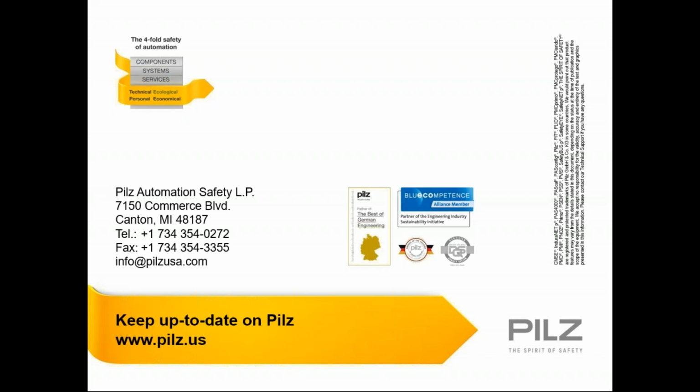Randy, this is Ben. The only thing I would mention very quickly is that in your pictures where you were demonstrating the circuitry for different category levels, the illustration shows 2 mechanical gate switches in order to meet the redundancy requirements for those safety categories. I would mention that if you use a higher safety rated, a category 4 safety rated switch, then you don't need to have 2 switches there. I just wanted to make sure that that was clear and no one was misled by the animation that you have to have 2 switches there no matter what.